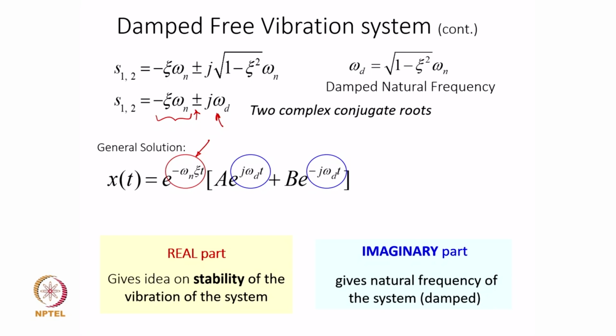And therefore, before we even jump into the forced vibration response calculation, it is usual for the designer to carry out eigenvalue analysis on the system, because through eigenvalue analysis you get all the roots of the vibratory system, and once you get the roots, you also immediately come to know whether the system is stable or unstable by just looking at the real part of the complex eigenvalue.